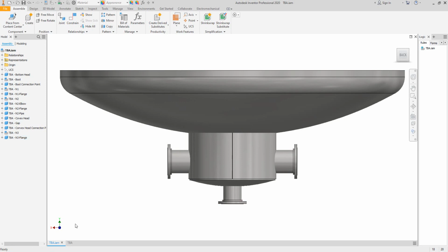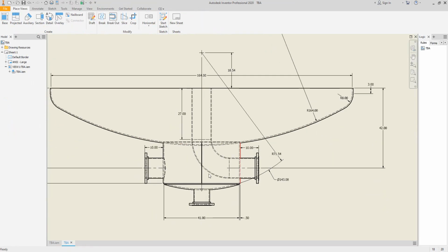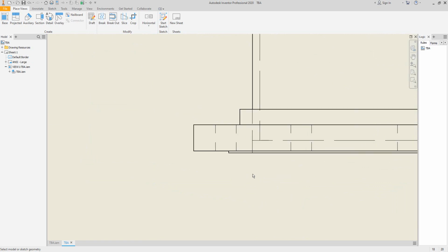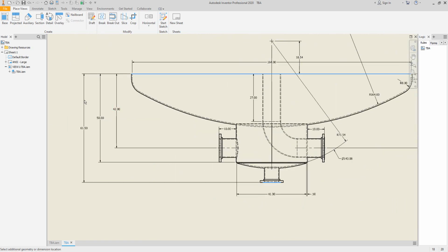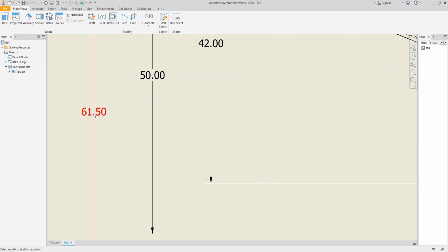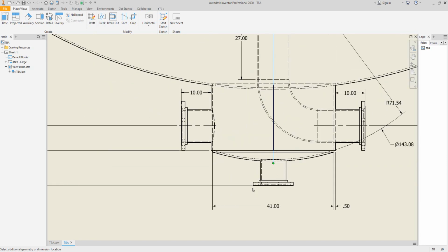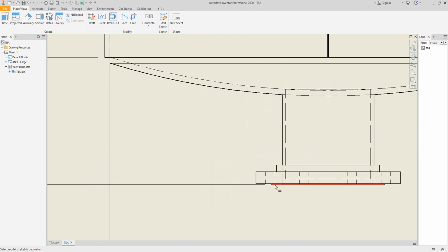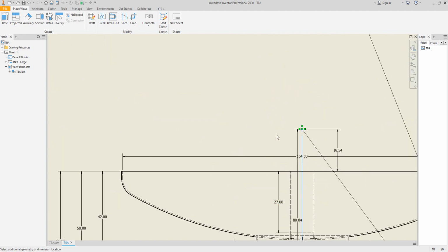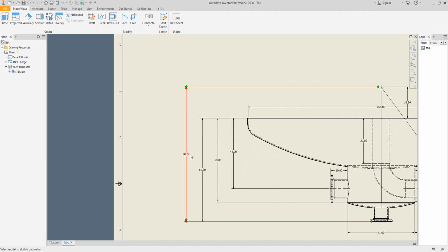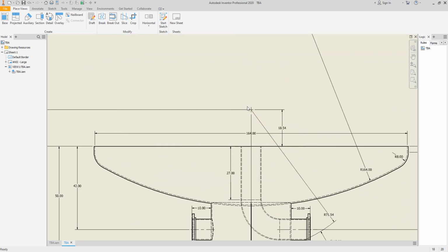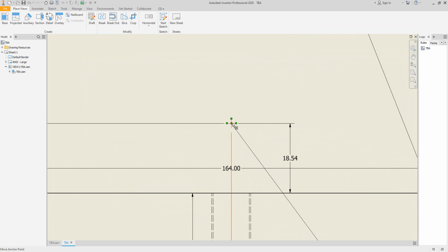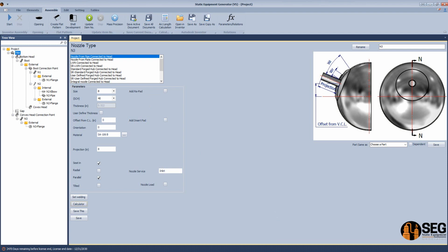Now we have this nozzle, and if we try to measure the values, as mentioned, we will measure the value from the face to the seam line. It will equal 1 point, because we measure the value from here to there. When we calculate the projection, we calculate it from that element. Now if you try to add a shell, you will actually start creating the shell from this point, not from that point. Let's try that and check how we can